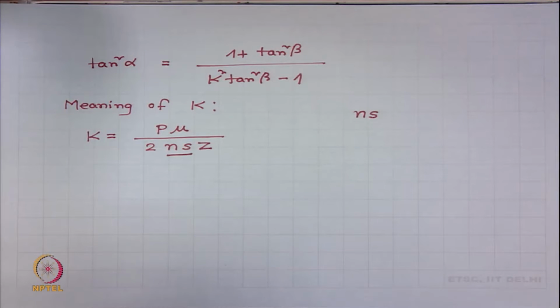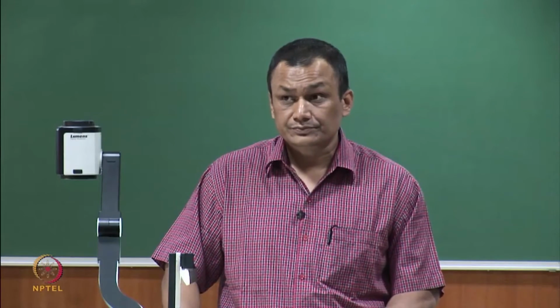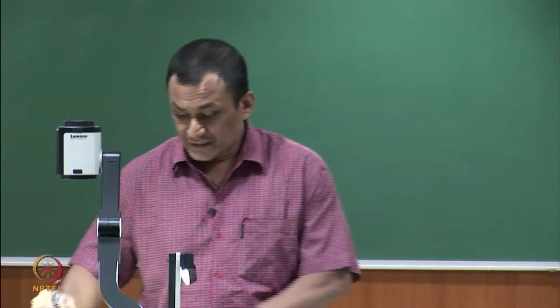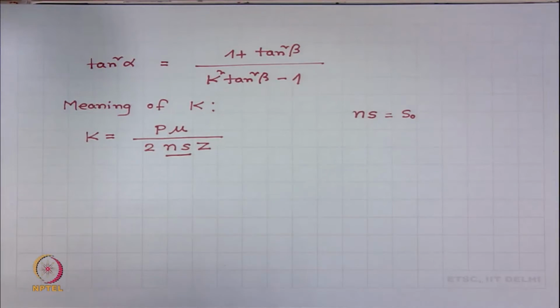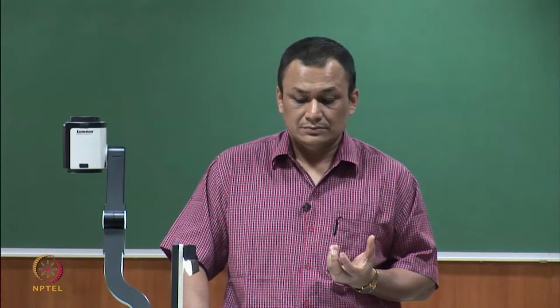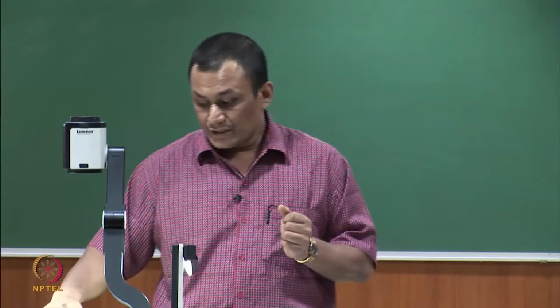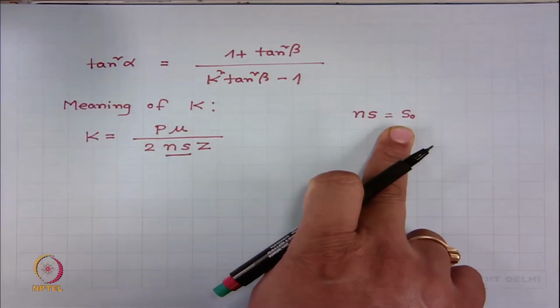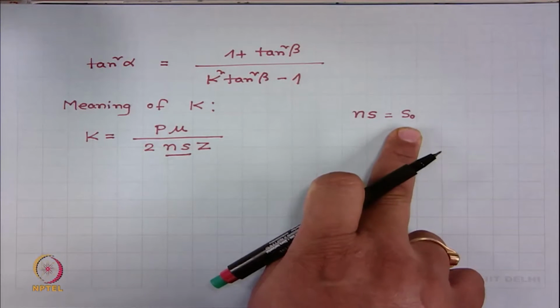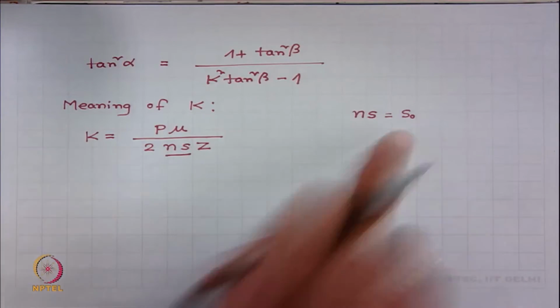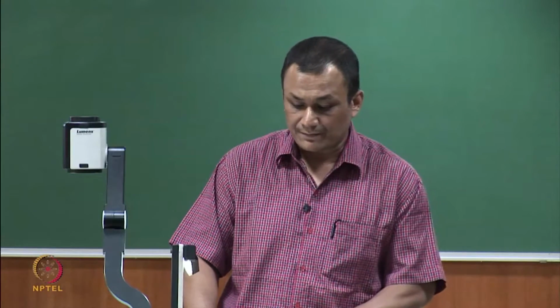The concept of substance area we introduced in module 2. So, this Ns we can write as substance cross sectional area of the non twisted fiber bundle. In module 2 we used capital S to denote substance cross sectional area. Here we use the same symbol with subscript 0 to denote the initial non twisted fiber bundle.